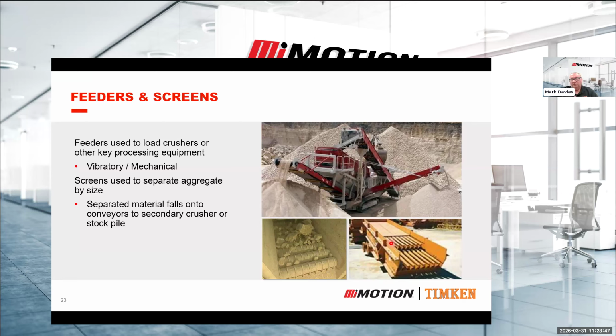So on this screen here, on the picture of this, this is a mobile screening plant, and you can see that it feeds into, that's the red section at the top, is the screen, and the output has multiple outputs. So it has this conveyor that is feeding out a particular coarser grain product, and this one is a finer grain product because it's a multi-deck screen. So these quite often are basically the finishing size. So they'll then use a wheel loader to come in and dig up that stockpile and then put it onto a truck, and that's basically on a quarry.